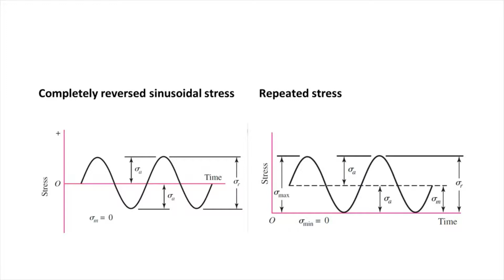This means we can no longer use the SN graph to estimate the fatigue strength. The reason is most basic SN fatigue data collected in the laboratory is generated using a fully reversed stress cycle. However, actual loading applications usually involve a mean stress on which the oscillatory stress is superimposed. A very substantial amount of testing is required to generate a diagram, and it is usually impractical to develop curves for all combinations of mean and alternating stresses. Several empirical relationships that relate alternating stress to mean stress have been developed to address this difficulty.